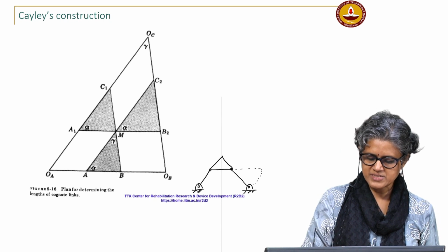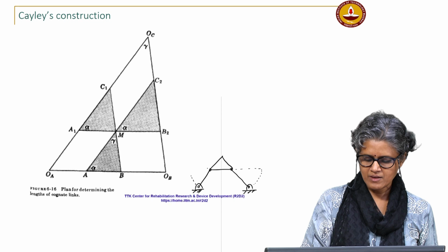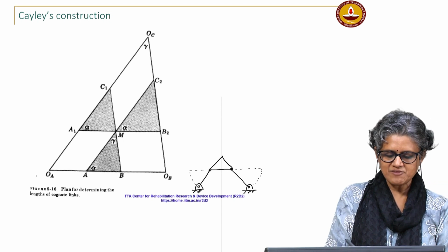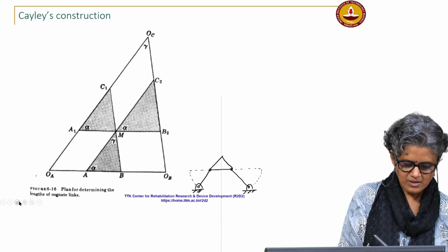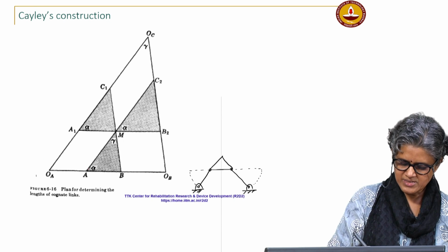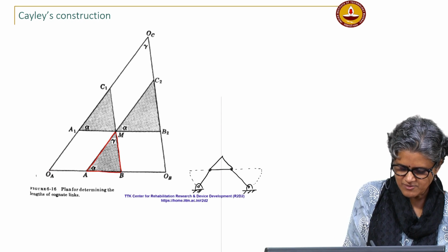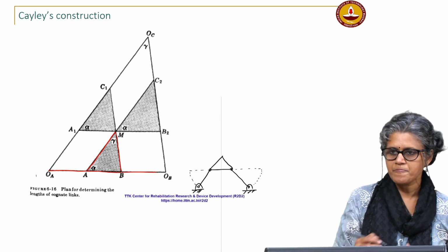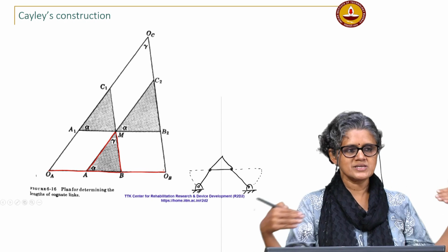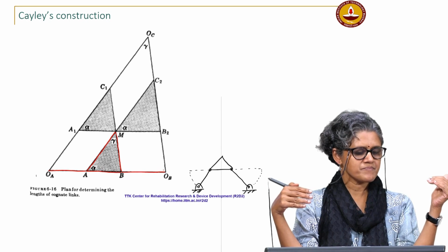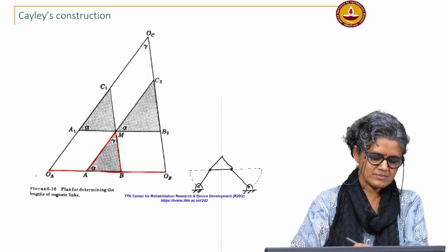Similarly, here disconnect it from the fixed pivot for the purposes of construction and you straighten it out. So, that is OA, that is this configuration here. What you see here is you have the coupler triangle and you have the linkage disconnected from its fixed pivots and flattened out with respect to the base of the coupler, and then you just construct lines parallel.